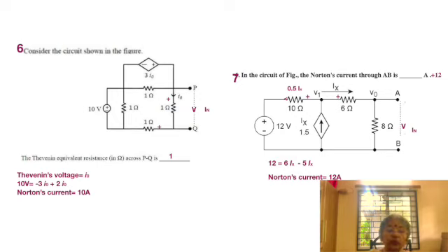It means that the voltage source that is dependent on it, which is equal to 3I0, is also equal to 3 into 0, which is a short circuit. So only 10 volt is now applicable across the 1 ohm resistor, as also across the other 1 ohm resistor, which is at the bottom and horizontally placed.